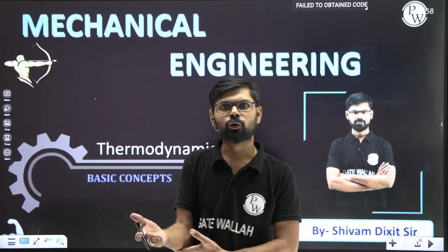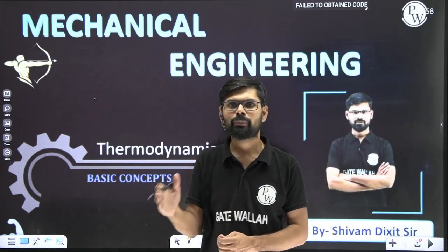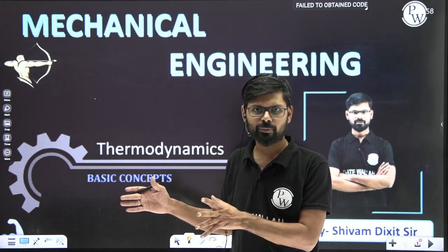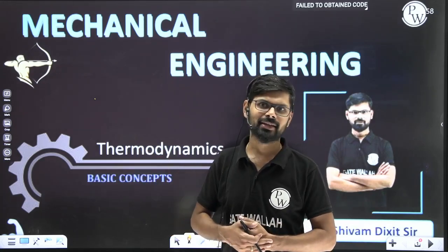Even in our real systems, whatever gases are used, right? Let's say a gas turbine or an IC engine, we are using air or an air-fuel mixture or something, and that is actually treated as an ideal gas. So these gases can be considered as ideal gas. What is the criteria, I'll tell you. In a steam power plant, in every situation you cannot treat it as ideal gas, but in this particular portion, like in gas turbines and IC engines, the working fluid is an ideal gas.